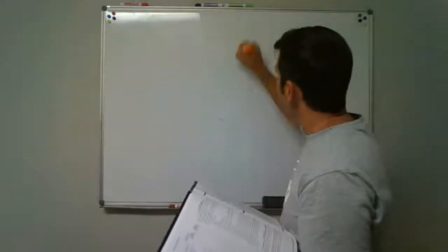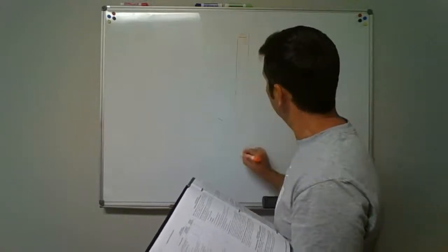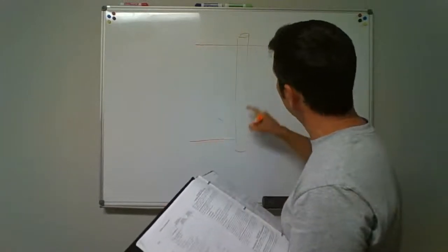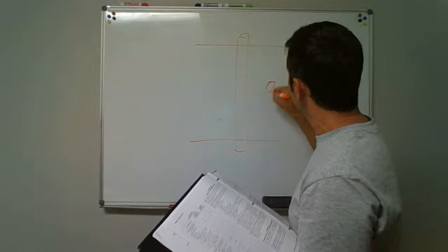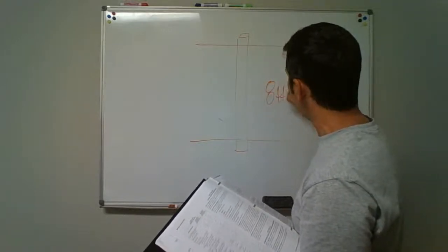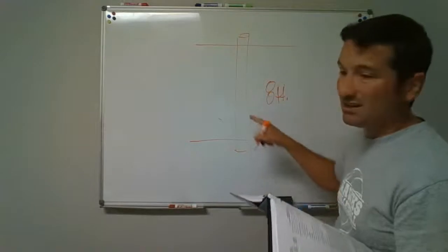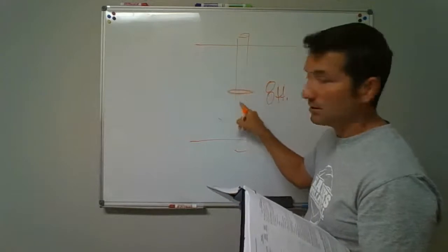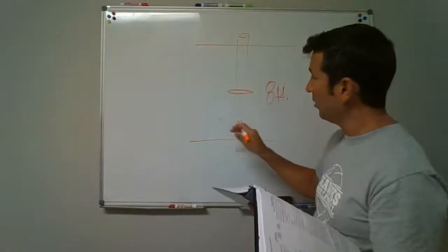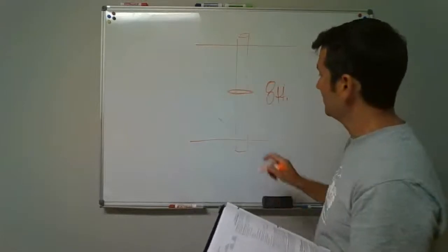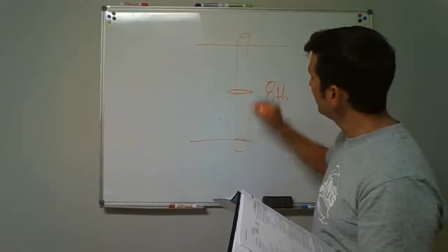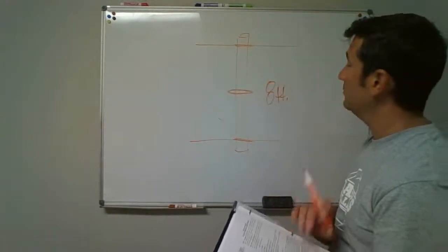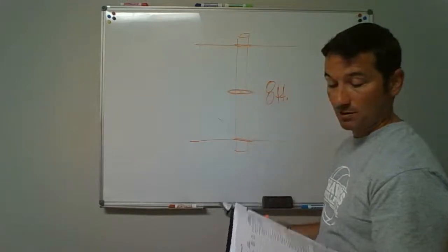So if we had a pipe that was passing, so there's our pipe. Let's just say there's the top plate of the wall. There's the bottom where it goes through. This gap is going to be, which we call 1 story, about 8 foot in between. If the pipe is 2 inches and smaller, it's going to want us to put a strap somewhere here in the middle. If we get up to 3 inches and bigger, we don't have to put that, but it states that there. So you're saying, oh, well, it's supported where it goes through the floor, supported where it goes through the ceiling. That's only 8. This says we can go up to 10 feet, but it says if it's smaller, you've got to put a strap right there, okay?